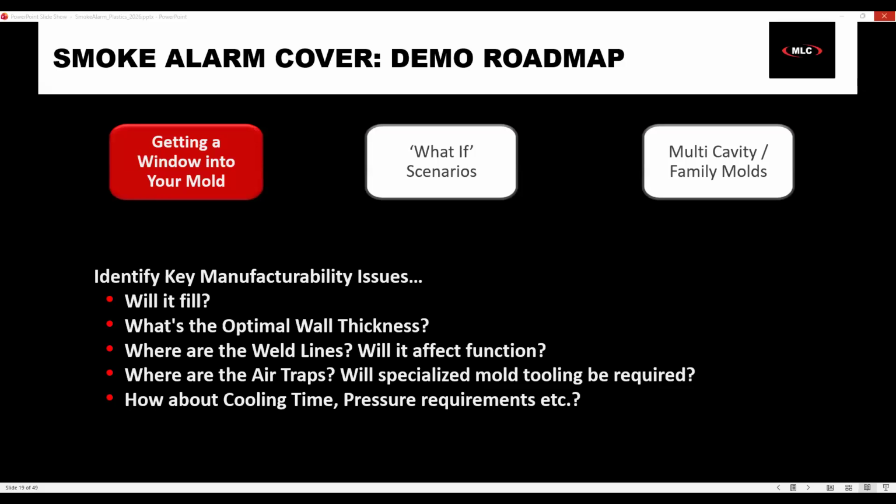It's filling really fast, and it's creating all of these different flow fronts. So if I move this to the other side, we can also see this here. Here you can also see how on this side, it's ahead of all of this. But what's going to happen is right here in the middle, you have this massive flow front that's creating there, and you're going to create really deep, potentially weld lines in that section. And we can actually see that, but we're just predicting that based off of being able to see how it's flowing through all these little tiny ribs.